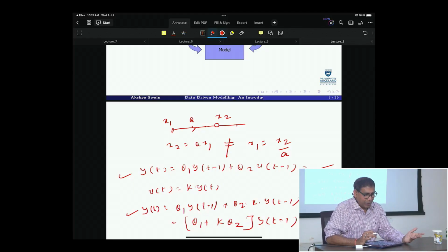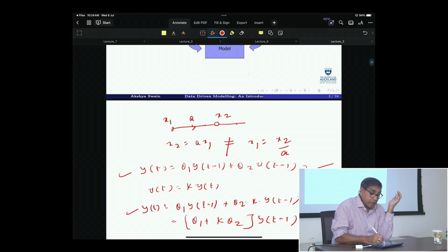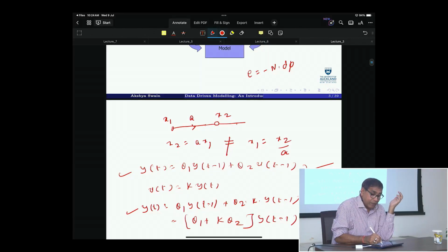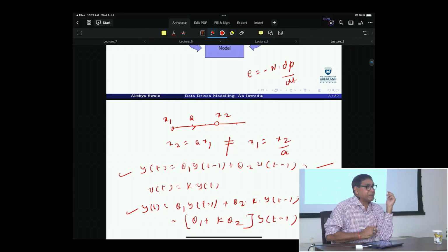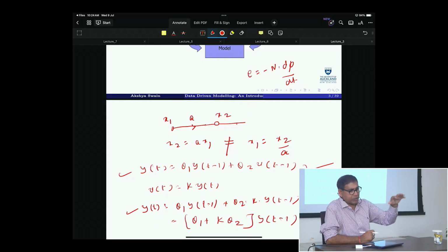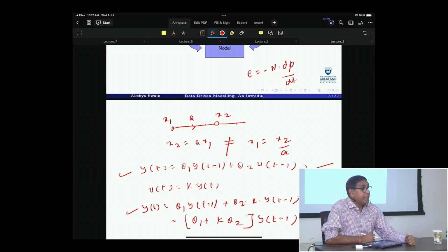You are all academics, so you can say what we teach: E is equal to minus n d phi by dt, electromagnetic induction. When I was teaching electrical technology in REC, and machine theory for 3 years in Auckland, I always said that the negative sign is not an arithmetic negative. It reflects Lenz's law, which tells that the effect always opposes the cause.